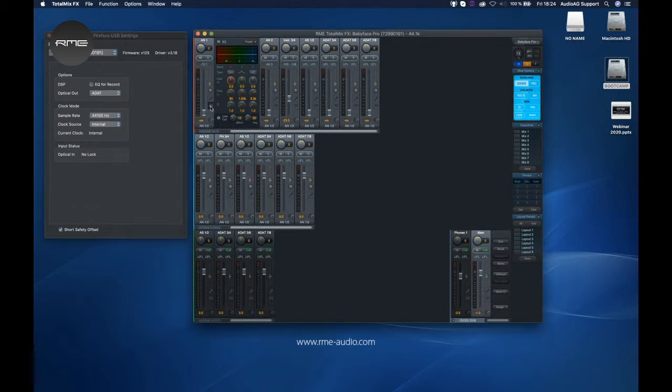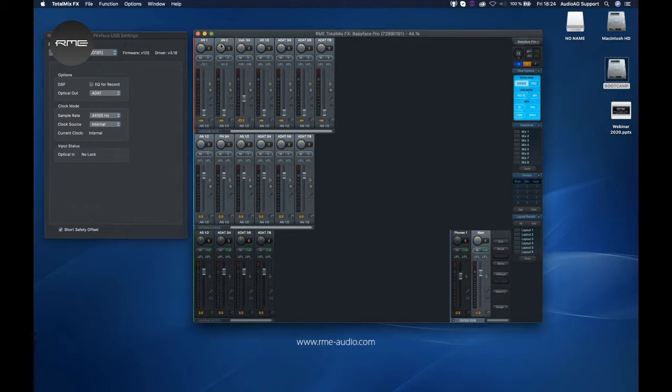So again, what do we have here? We have our two microphone inputs here. We have instrument and high Z inputs. We have digital inputs over here. Just have a look at our hardware input. You have this wrench here, and you can open it up, and you see a few functions. Now, I have a test tone generator connected on my analog input 1, and it needs phantom power like a condenser mic, so I can give it phantom power, and I see I have a signal here.